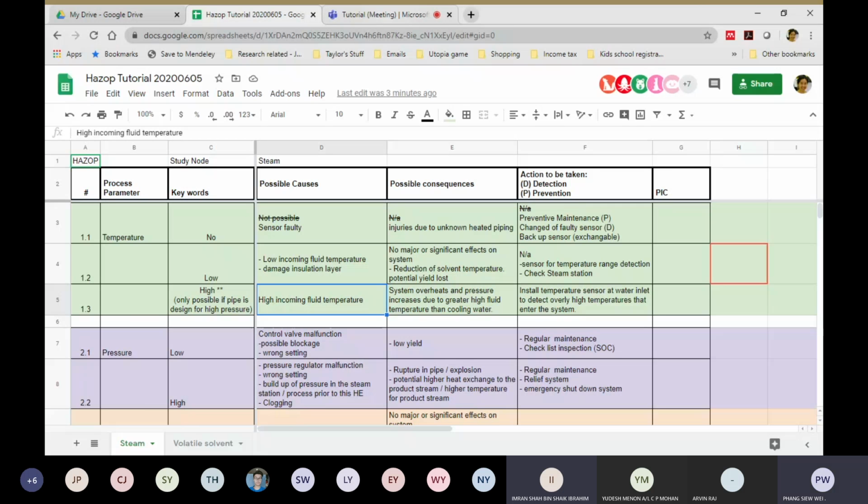Yes. So when we first run HAZOP, you don't perform it on your own. HAZOP is always group work. So you get someone that is experienced in that area, meaning you can engage a consultant. You can get the senior engineers who have worked with the system before as part of your team. So normally HAZOPs will have a team of engineers, the process engineer, the service engineer, and in fact, previously when I was working in industry, I always liked to engage 1 or 2 operators or their line leader, because they are the ones who are hands-on.